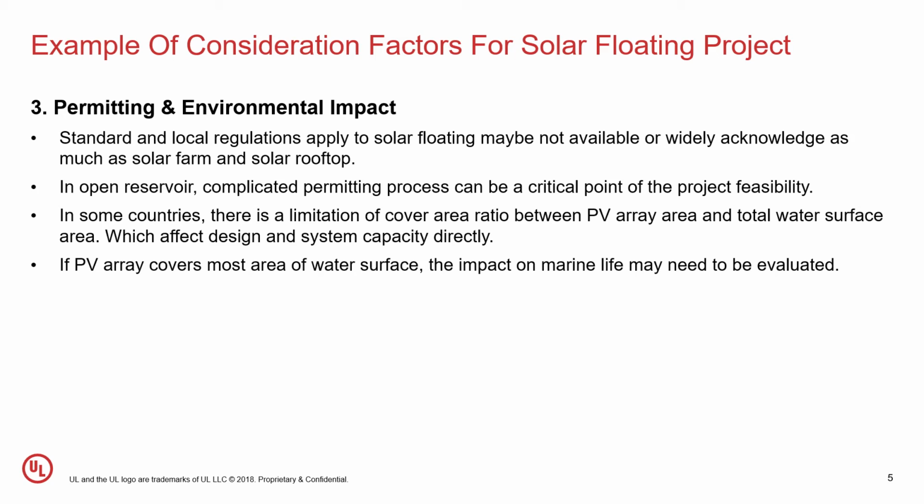Then we faced experience before in some countries where the local regulation specifies the cover area ratio between the PV array and the total water surface area, and you have to take this into account because it may affect your project capacity. And if your PV array covers most of the area of the pond, in a country or market that is very strict on environmental impact, you may be requested to make a study report about the effect on marine life.